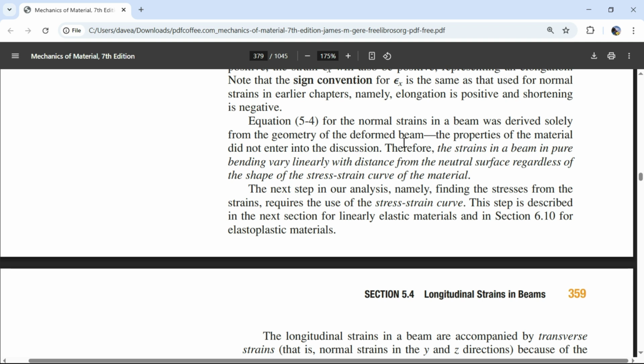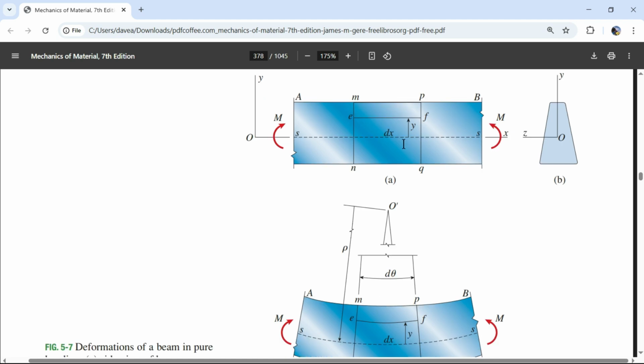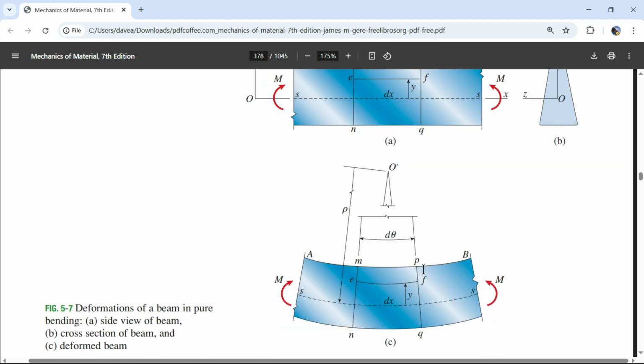And in between any two little points, these dx points, I can actually say, so let's go back to that. Just from nature, if I see a beam and it's curved, I can take a point right here and a point right here, measure the tangent, and then measure the new tangent, and say, yeah, I think the angle changed. And I know that change in angle has to be part of a circle.